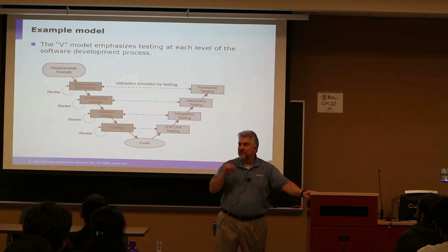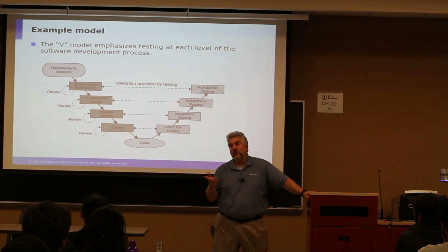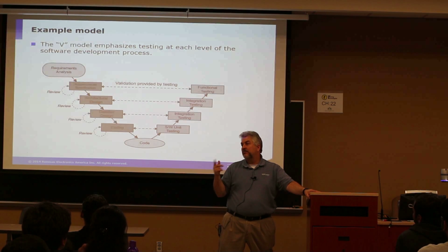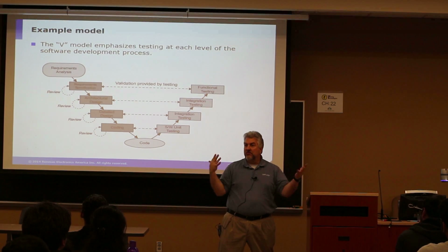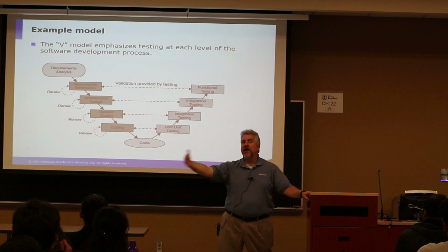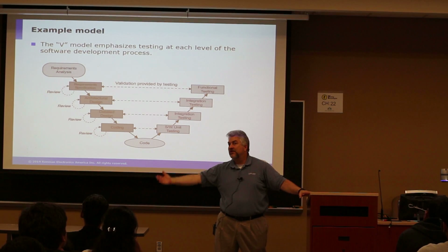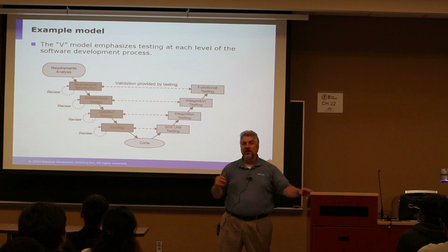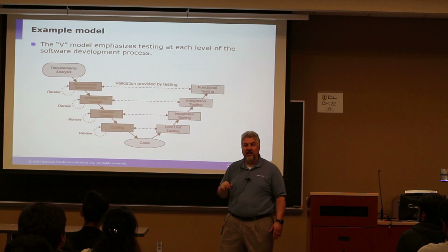Some chips have it already built in. And you're going to have the same concept where you'll have to keep track of time. The time of day clock will do that for you automatically. It'll update every second, actually probably every millisecond. Otherwise, you'll have to write software for that. So sometimes knowing that up front, like are you going to have a timer or a time of day clock, is important because that'll determine how your design is done later, right?